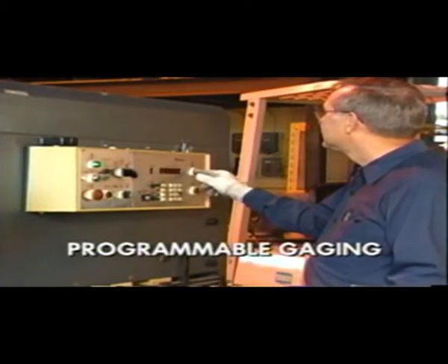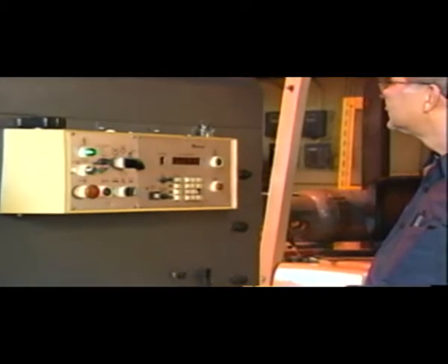Programmable gauging is highly accurate and is incorporated into most CNC shearing programs. Sharpness of the knife plays an important role in the edge quality of the part. A sharp shearing knife can cut tough materials because the sharp edge concentrates the shearing force in a very small area of the workpiece. Dull shearing knife edges deform the metal surface more than sharp edges, since the shearing stresses are spread out over a larger area.